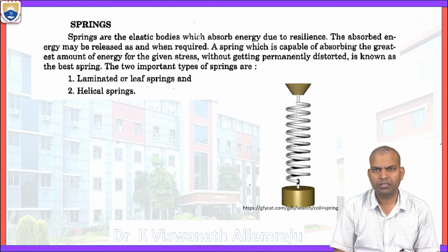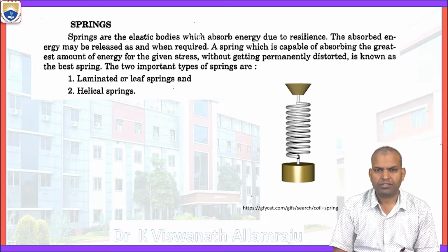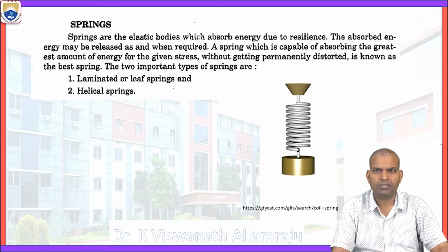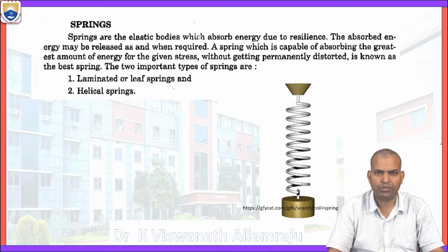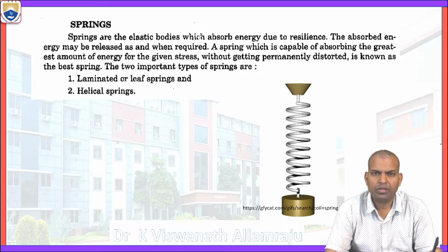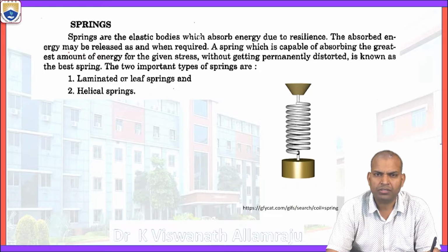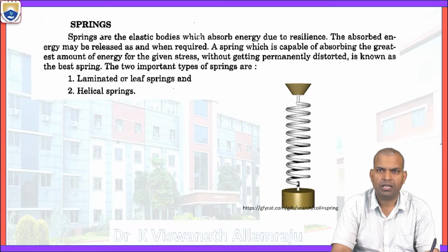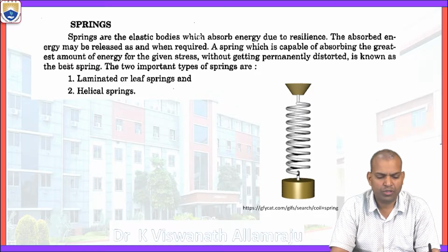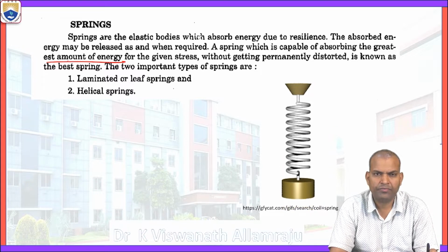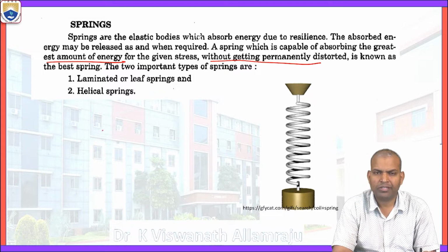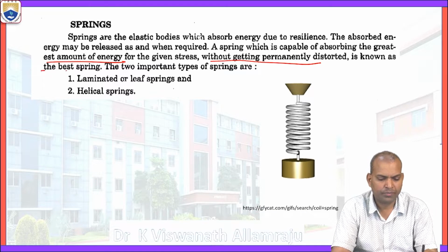Now consider the purpose of springs. What is the introduction of springs? Springs are elastic bodies which are used to absorb energy due to resilience, and the absorbed energy may be released as and when required. A spring which is capable of absorbing the greatest amount of energy for a given stress without getting permanently distorted is known as the best spring.